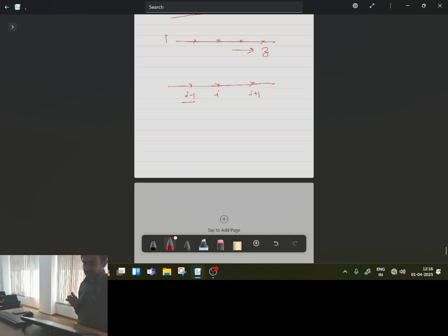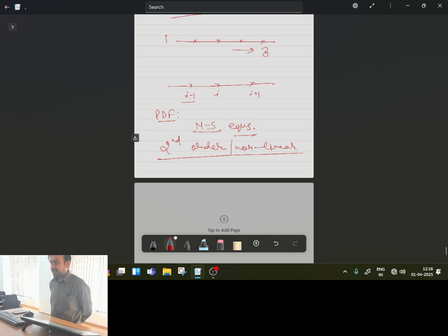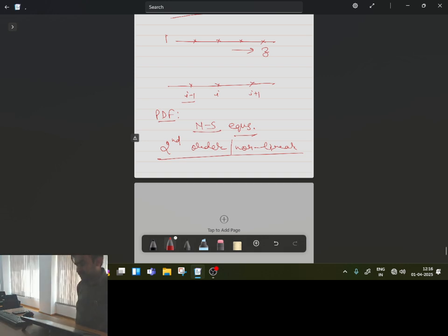Typically the governing equations of fluid flow and heat transfer are partial differential equations, and if I simply talk about the Newtonian fluid, then equations are typically known as Navier-Stokes equations. If you see the mathematical nature of the Navier-Stokes equations, these equations are of second order and these are non-linear equations. So equations for solving fluid flow and heat transfer problems are nothing but second order non-linear differential equations. Is this one clear?